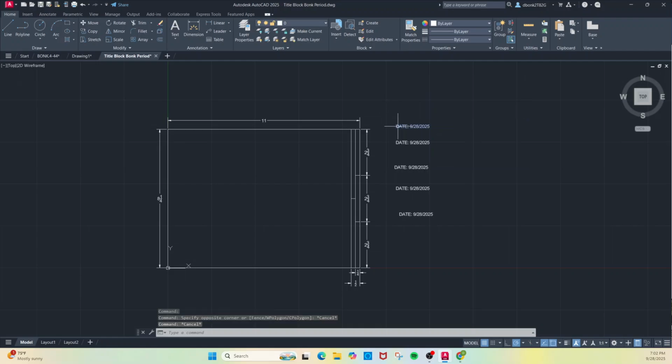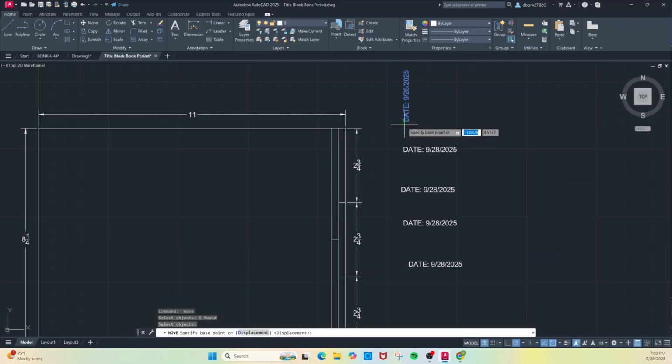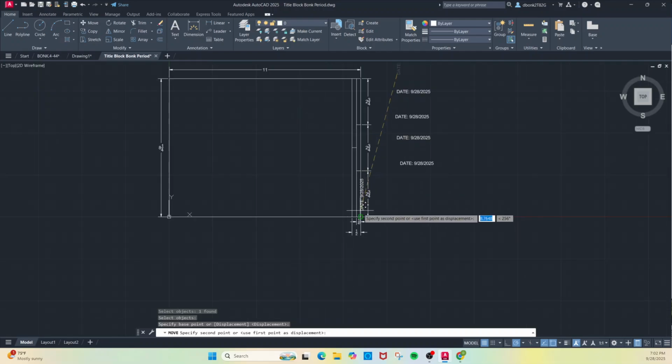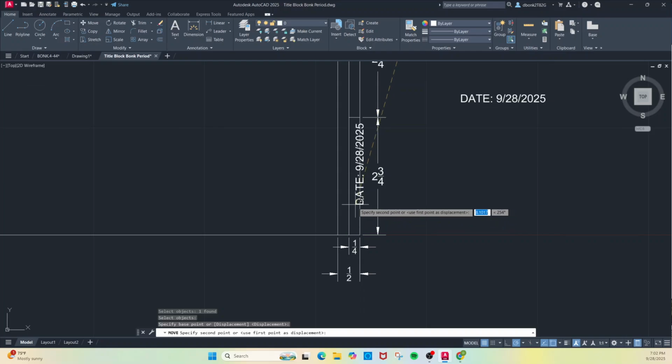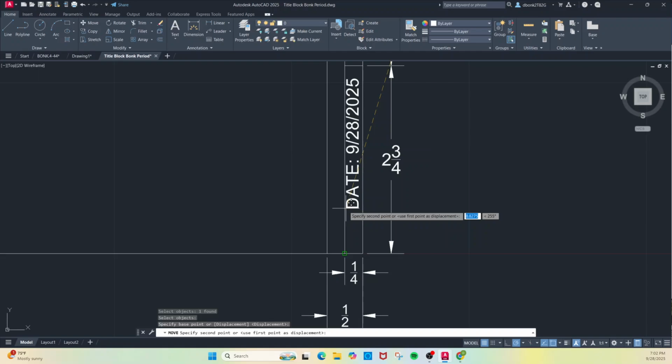Now I'll show you just how to rotate and move these. You're just going to rotate by clicking rotate. Okay. I'm going to do that over again because really if you click rotate, you have to select the object, then hit enter, and then click a place for it to rotate on, and then it'll spin. Just so you can see how that's done for the other ones. And then move is similar, where you click on the object that you want to move, hit enter, and then you have to click a place where you're going to move it from. Grab it from a corner. The closer you get when you place text or move anything, the better.